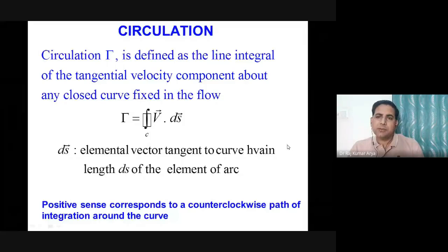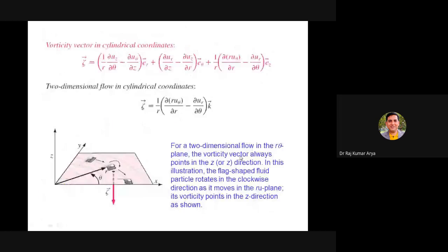That is easy to approximate or calculate, because you know the velocity on top, you know the velocity on the bottom is zero, and you know the depth, so you can calculate the slope. You can get the equation of the line in terms of velocity. So that is easy to calculate. From there you can calculate the height where you will put a divider, so that you can divert the flow as per your need. So we did one example for that also.